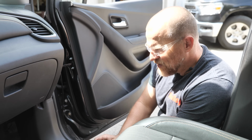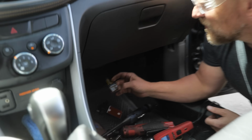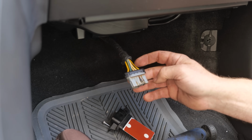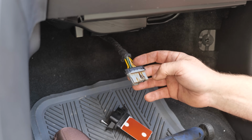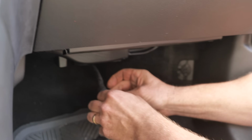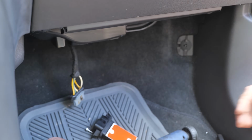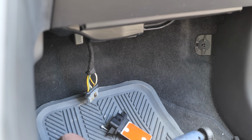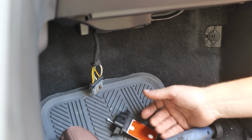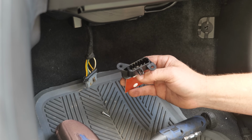What we want to do is ground this white wire here, the white wire that comes from the blower motor itself. I'm going to ground that, and then I want to measure amperage on what I'm grounding. So we'll get an amp clamp here. Why are you measuring amperage on it? I want to know what my blower amperage is, because if that blower motor is failing, then there's too much current flow for this. Yeah. It could honestly just be a crap part.